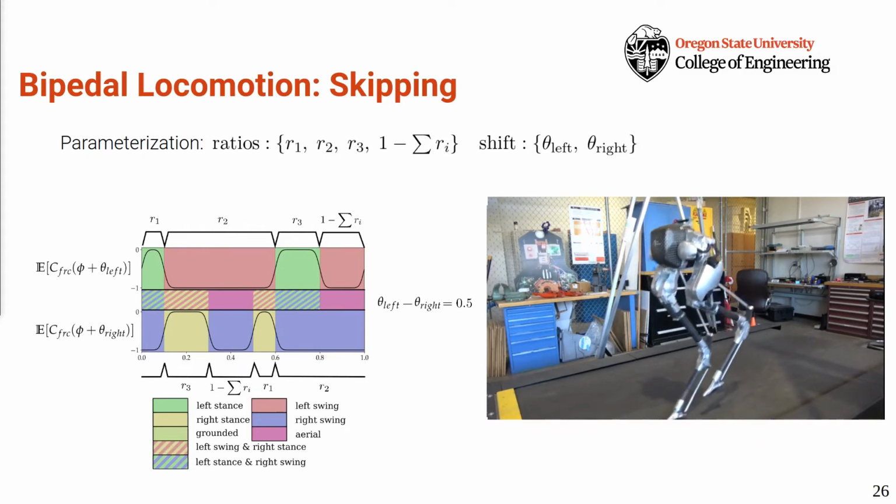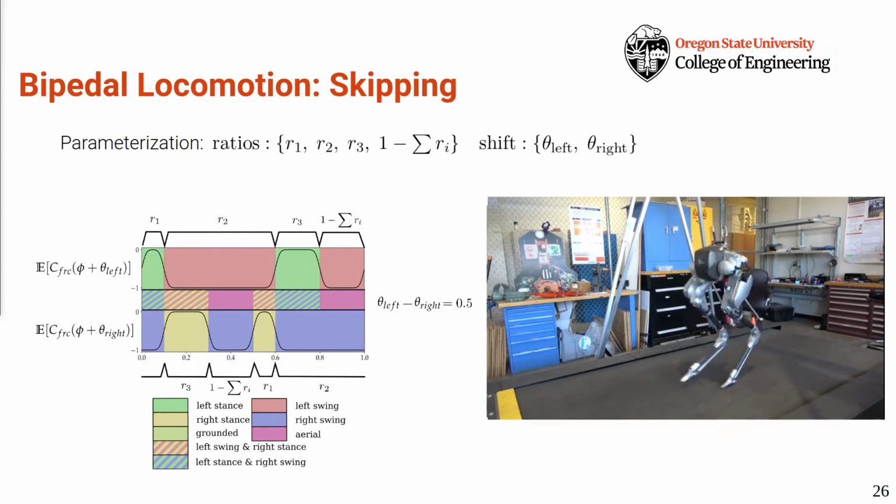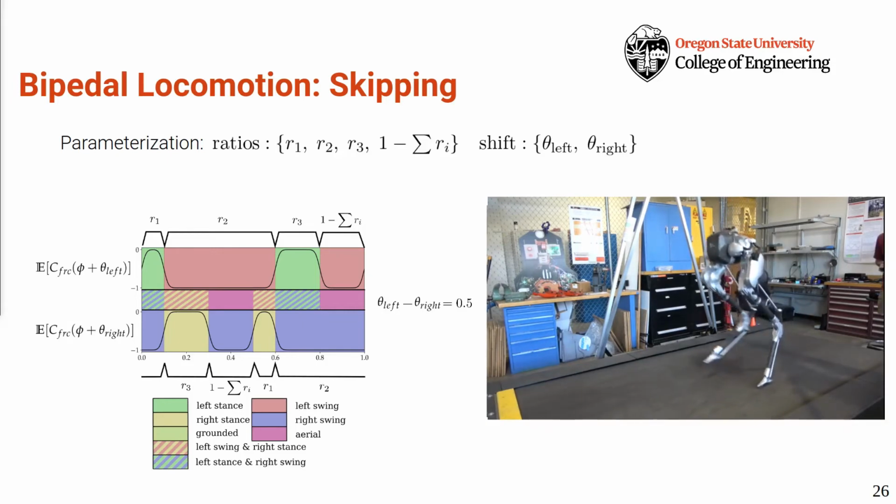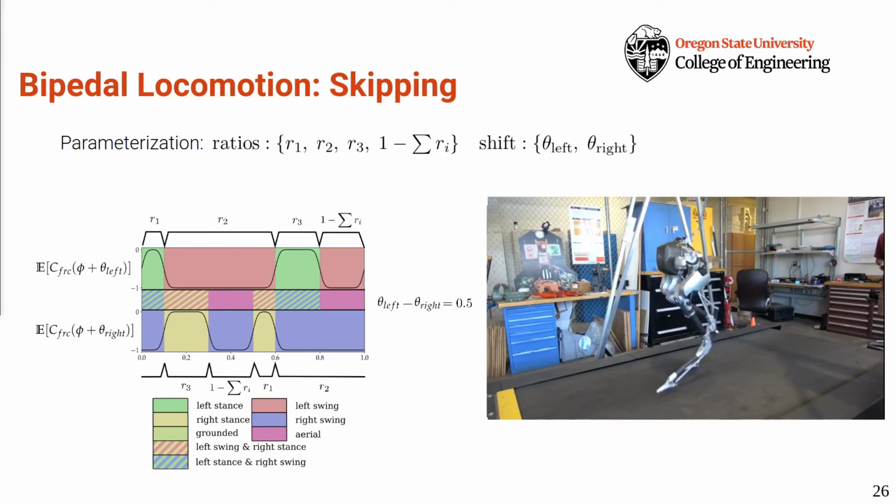This extension of the framework is capable of expressing more complicated gaits such as skipping, but is also more sparsely populated with feasible gaits. While the reasonable training procedure for the 2-phase model would be uniformly sampling commanded ratios and period shifts, doing so in the 4-phase space results in sampling many more infeasible behaviors for the robot. In practice, we defined reasonable ranges for sampling commanded behaviors, and the learned controllers were capable of transitioning between any behaviors in that sample space.